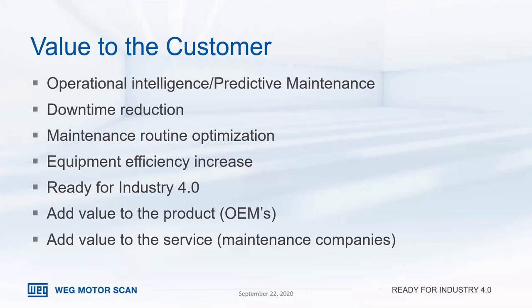Vibration, greasing the bearings, making sure that the motor's clean, so you're not increasing the heat within the motor, because with a motor, everything's thermal. The majority of failures are either a bearing failure, which is a lot of times due to heat, or contamination. So it's all environment and application of the product. So that third bullet is where I would lay the WEG Motor Scan product, is really to help drive maintenance.